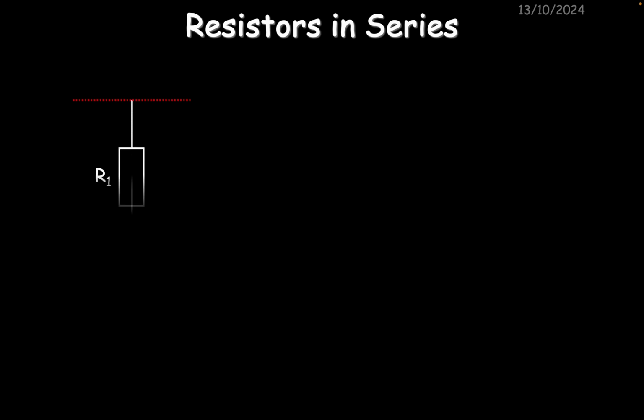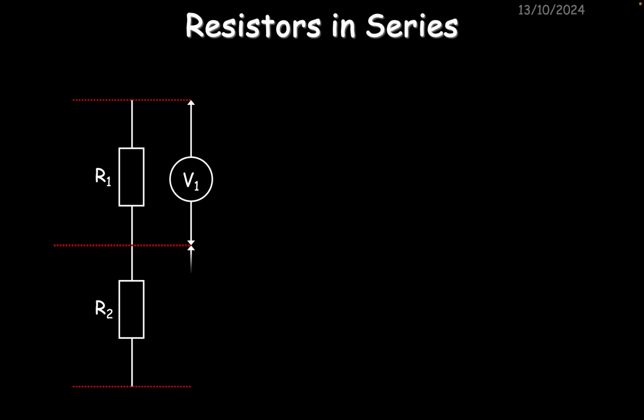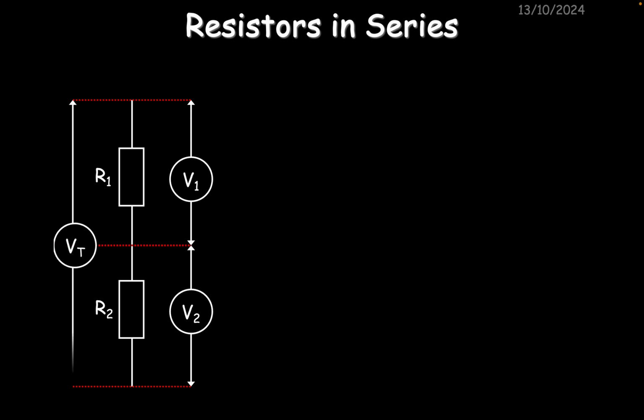Okay? So resistors in series now, as I said, if you've got 2 resistors in series, you just add them up. The reason is the current is the same through both of them, but the voltage across them could be different because each one will get a different voltage if the resistances are different. So this is just a part of a circuit. For A-level, you need to be able to show this proof, which I'm going to do now.